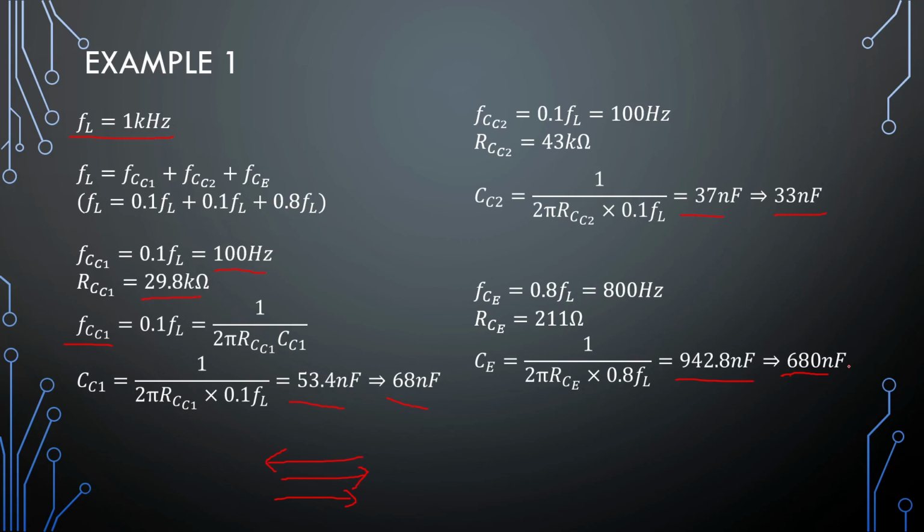So I went with a lower value right here. If you pick this 1 microfarad right off the bat while you're designing, that is okay. There's no problems with that. I chose a lower value because I did the simulation on this and saw the effect that this 1 microfarad capacitor had in this position.